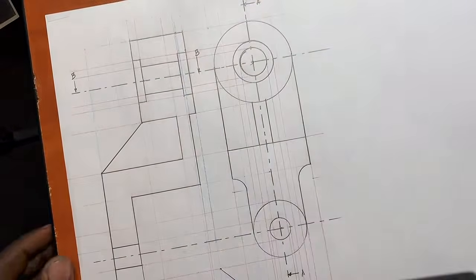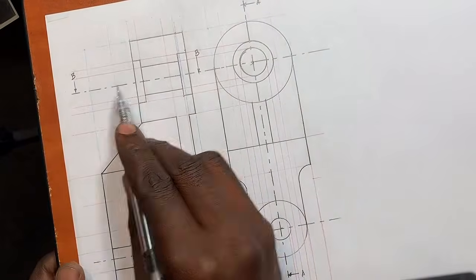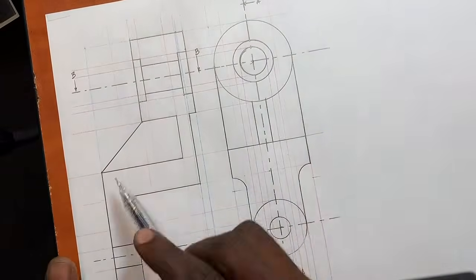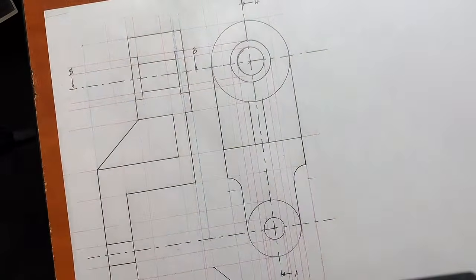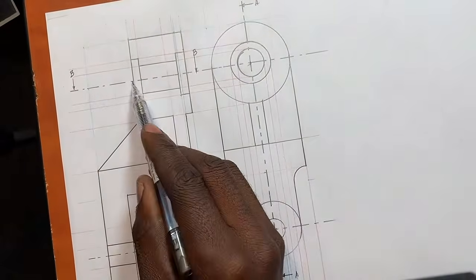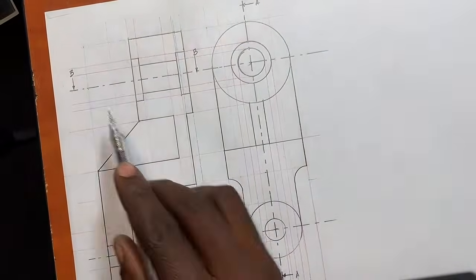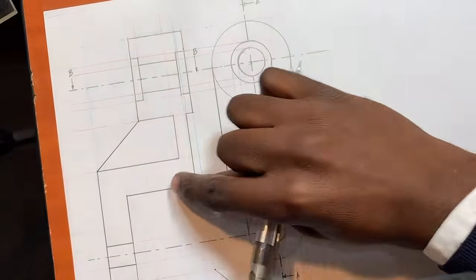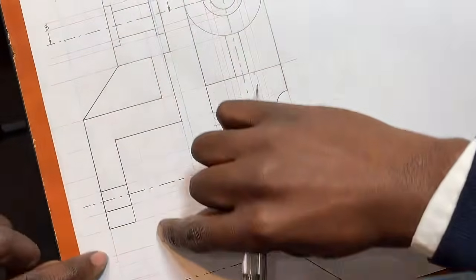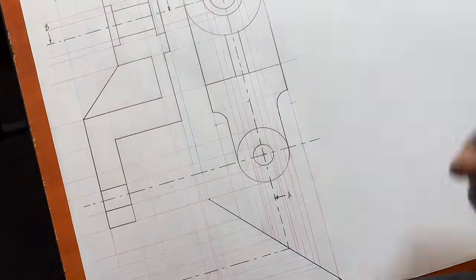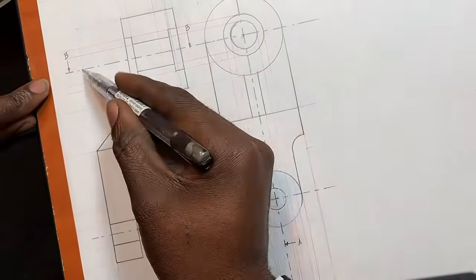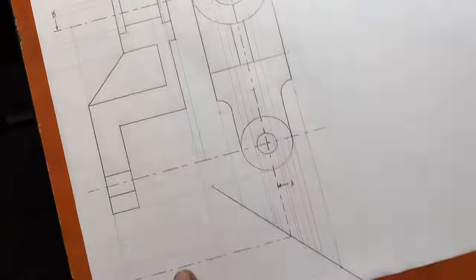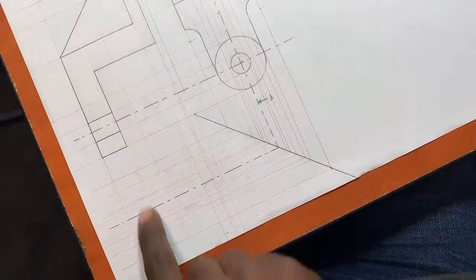I don't actually like it to start here. I normally like to start it to cover the whole particular view, so that when we are tracing the cutting plane, it will be like the hacksaw blade from here till here was not cutting anything. From here till here was not cutting anything, which means this gap, going down to your top view, mustn't have hatch. So trace it how? From here till here, you mustn't have any hatch, because the hacksaw didn't cut anything.